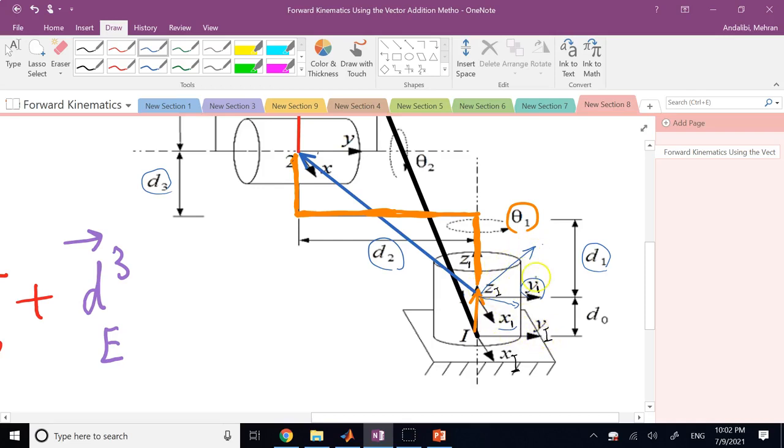And the displacement is definitely along this y1, which is opposite to this member, because as I said, your member is now going to look like this. For example, this is going to rotate too. Okay, so this displacement d2 clearly is opposite to y1, not yi. So it's better that we are writing everything with respect to the axis of frame 1, not with respect to the axis of frame I.